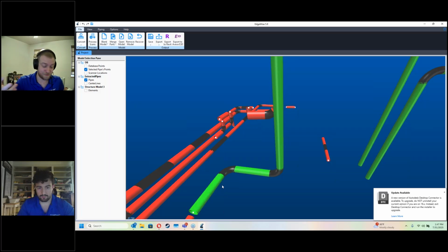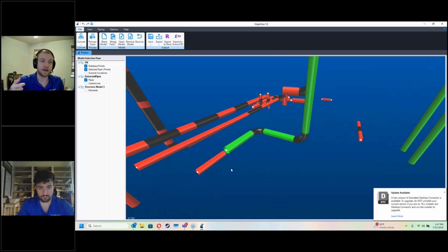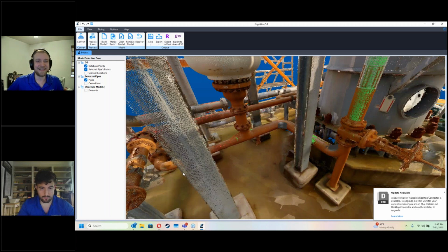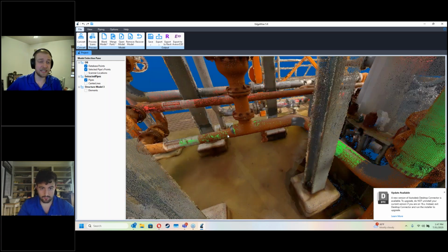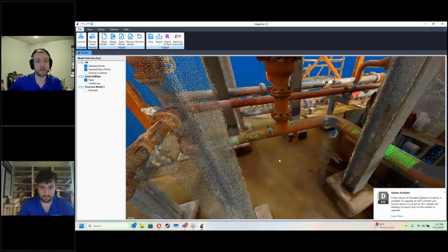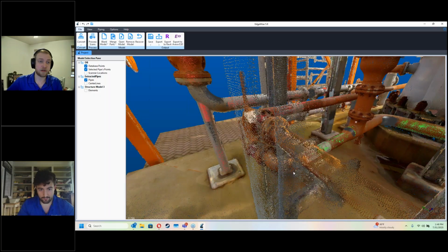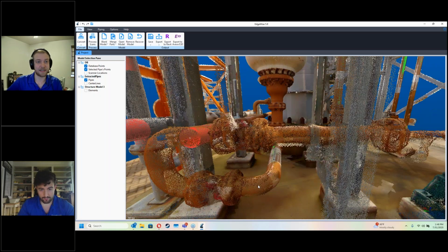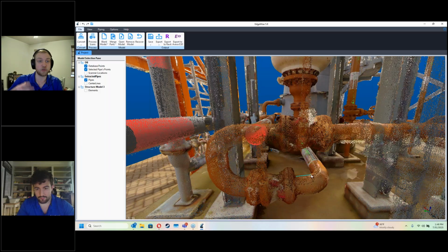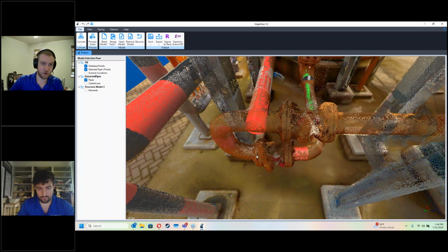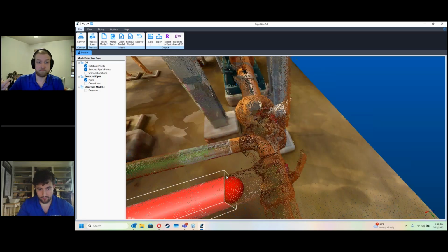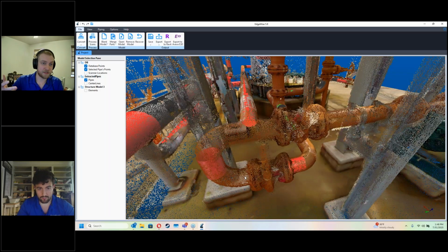But if, for instance, and this happens a lot, you forget to model something inside of EdgeWise, instead of having to restart because you can only import your entire model again, now you're able to model that thing you missed, select it inside of EdgeWise and hit the export button, and it will only export that pipe run that you missed and push that out to the export functionality. So when you import that in, it's just going to import that one pipeline. Or whatever you have selected.